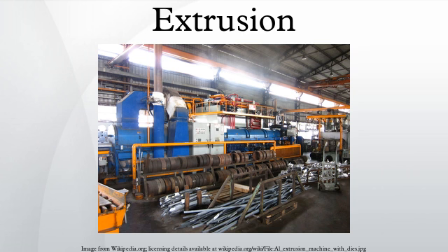Because of this, the greatest force required is at the beginning of the process and slowly decreases as the billet is used up. At the end of the billet, the force greatly increases because the billet is thin and the material must flow radially to exit the die. The end of the billet is not used for this reason.